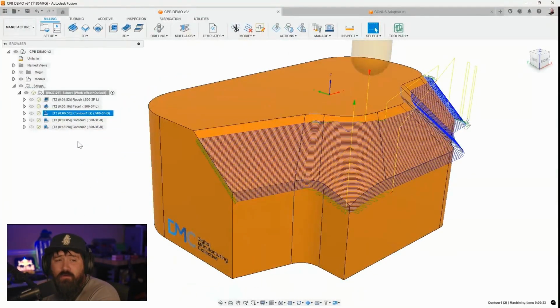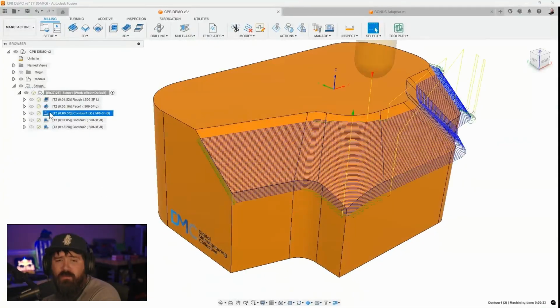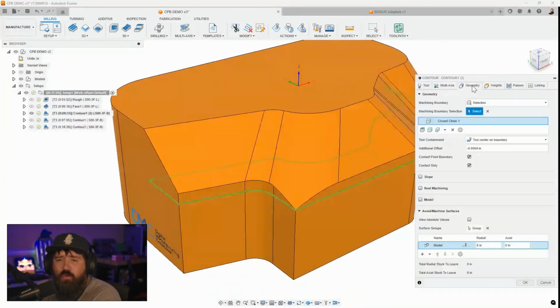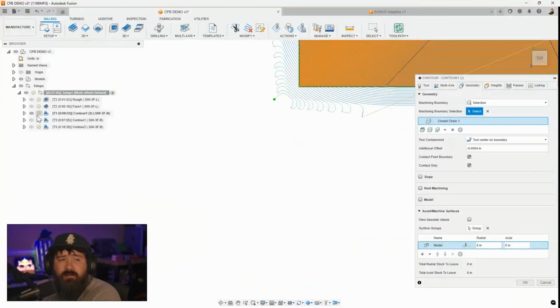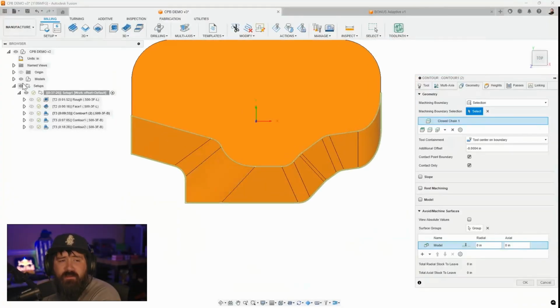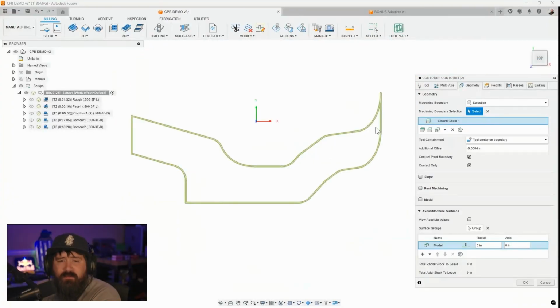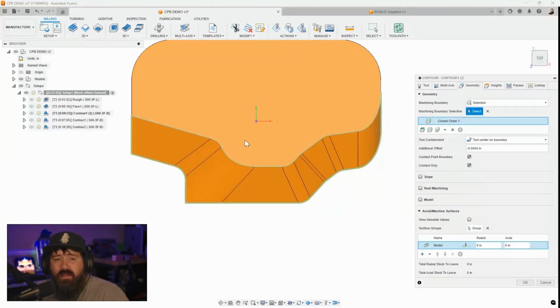The next thing I wanted to show real quick was, we talked about boundaries a little bit. This is obviously how we'd create this toolpath. We go to the top here. Let me turn off the eyeball. You can see this is the area that we picked for the tool to stay within, right? This is how we drive the toolpath. And this is going to give us the geometry area or the spot that we want to machine from the tool axis orientation. We're pretending to be the tool right now, and we're looking down at the part, right? Z positive is facing towards the camera.